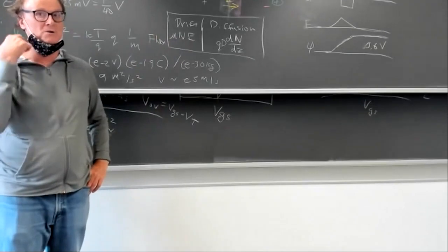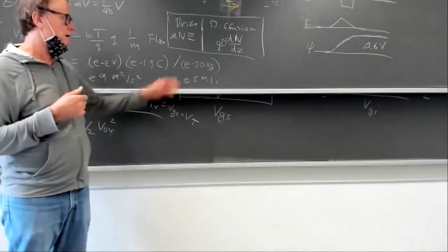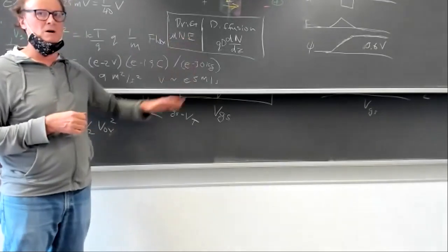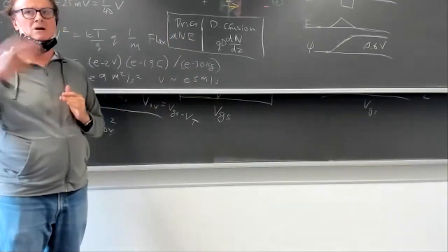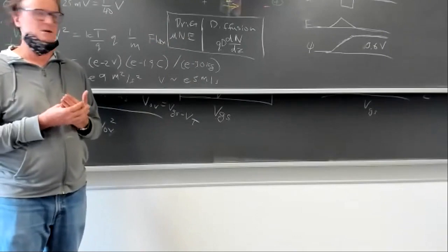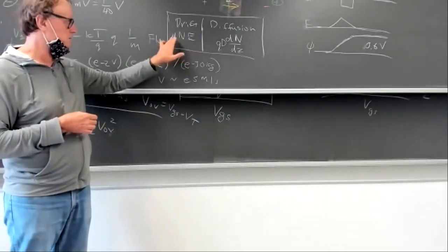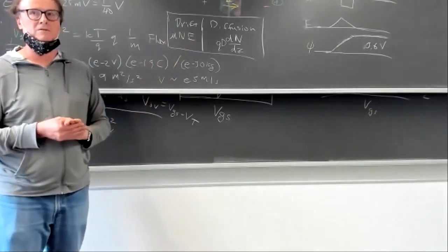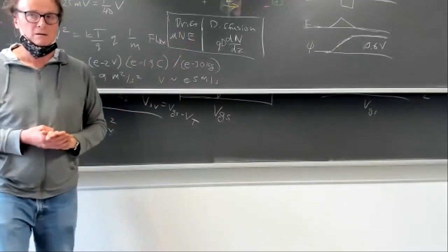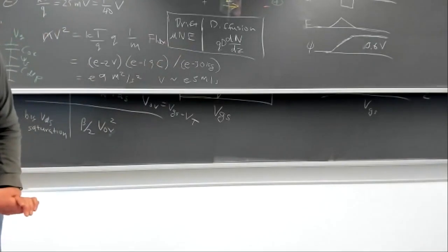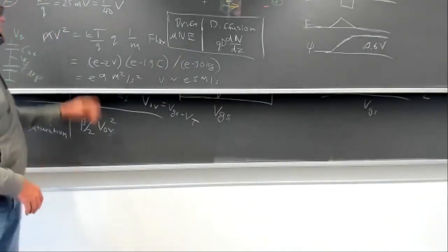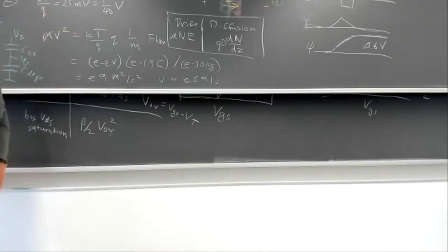And actually, that's true for a lot of digital transistors now. The current is not proportional to electric field anymore. It just becomes constant with electric field. But this assumes for a small electric field that the drift current is just proportional to electric field. Is that what you're asking? That we only consider under the assumption of small electric field. Yeah, just a small electric field. Anyway, that's what you've assumed here, right? Small VDS.